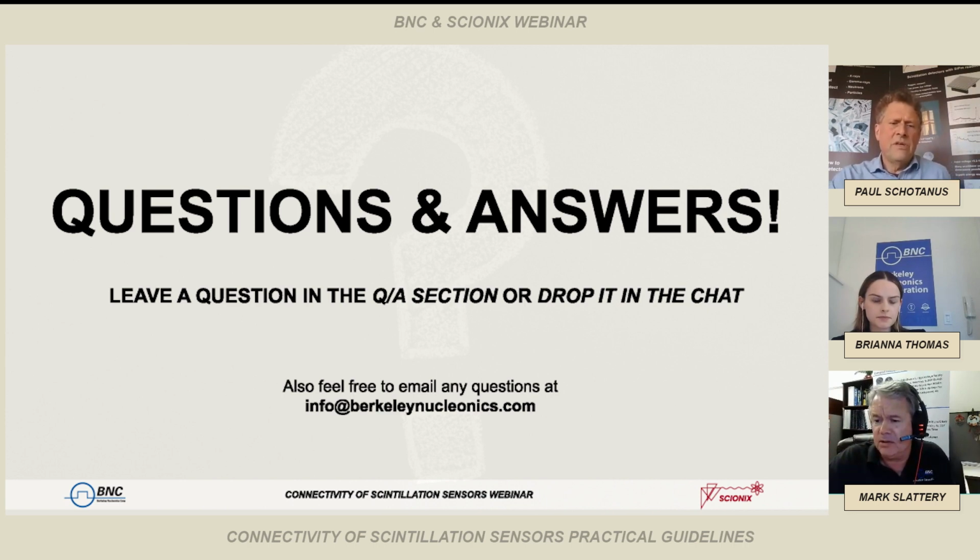Well, both. If you connect the silicon PM signal to an oscilloscope and you push the 50 ohm button, you see what happens. It will collapse a little, but not as dramatically as a photomultiplier tube signal, because a silicon PM by itself already has a significant capacitance. As a rule of thumb, your signal collapses in amplitude by about a factor of 3 maybe, but you still have a lot of amplitude left over, and it becomes, of course, faster. That's a fact.